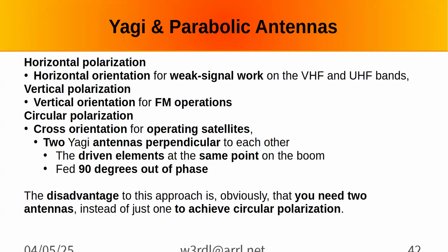Okay, polarization. Normally you use horizontal to do DX or weak signal work on HF. FM operations like VHF, UHF typically does vertical. Whichever way you're going.